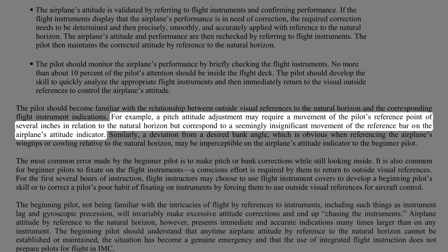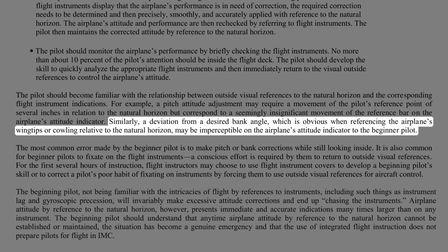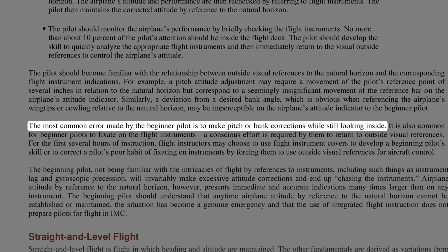For example, a pitch attitude adjustment may require a movement of the pilot's reference point of several inches in relation to the natural horizon but correspond to a seemingly insignificant movement of the reference bar on the airplane's attitude indicator. Similarly, a deviation from a desired bank angle, which is obvious when referencing the airplane's wingtips or cowling relative to the natural horizon, may be imperceptible on the airplane's attitude indicator to the beginner pilot.